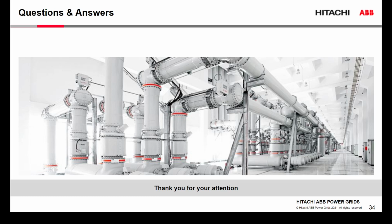The monitoring systems are a nice add-on. You have a lot of SF6 compartments, and it is of advantage to see any trending on the SF6 values. If you see any trending on a possible gas leak, you can react early, avoid the losses, and also do better planning of your maintenance. But there is no standard which requires a monitoring system.